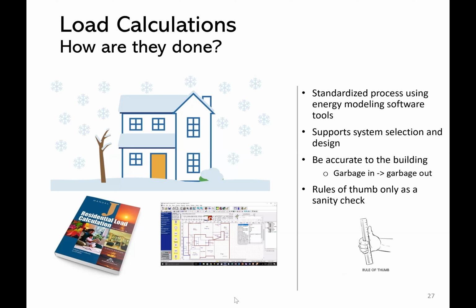Many of the software programs that are approved by the ACCA include local weather data that designate the design outdoor air temperatures for heating and cooling used to perform the load calculation. The collection of data for a particular home that is used as an input value for the load modeling must be done carefully and completely in order for the program to calculate precise thermal loads. The rule of garbage in results in garbage out is applicable. If the inputs are incorrect, then the output will be incorrect.